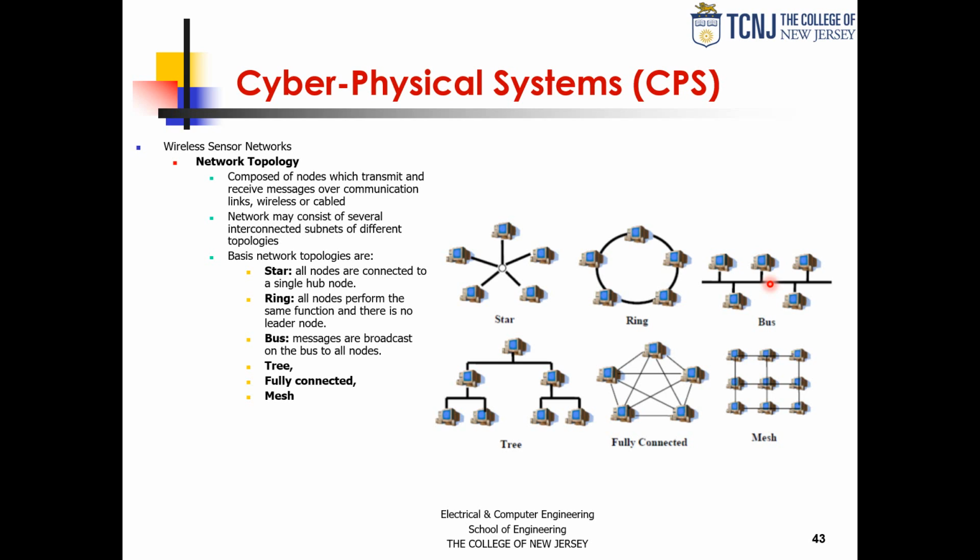The drawback is that you have to deal with things like collision because there is no synchronization of all these different entities on the bus. They're all just going to transmit. So you have to figure out ways to smartly deal with that.